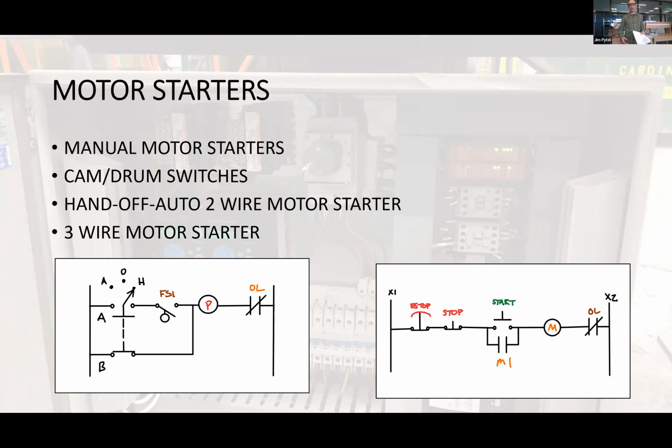In the event that that float switch is closed and it's in auto mode, if that motor overloads, the normally closed overload contact on the right is going to open up and stop the motor, okay? However, if that float switch is still being triggered when that overload cools and resets in auto mode, the motor will instantly start. So it's a very, very important concept for them to understand safety-wise. You need to actively lock out and tag out that system, okay?